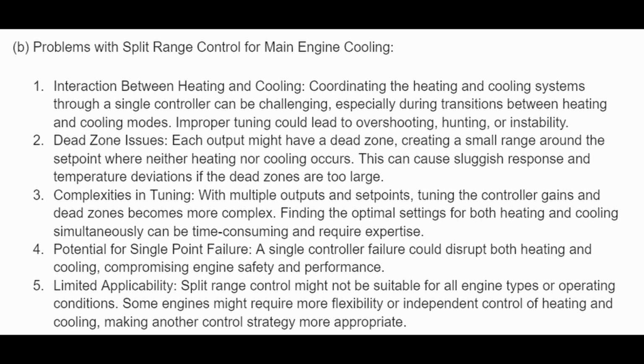4. Potential for single-point failure. A single controller failure could disrupt both heating and cooling, compromising engine safety and performance. 5. Limited applicability. Split range control might not be suitable for all engine types or operating conditions. Some engines might require more flexibility or independent control of heating and cooling, making another control strategy more appropriate.